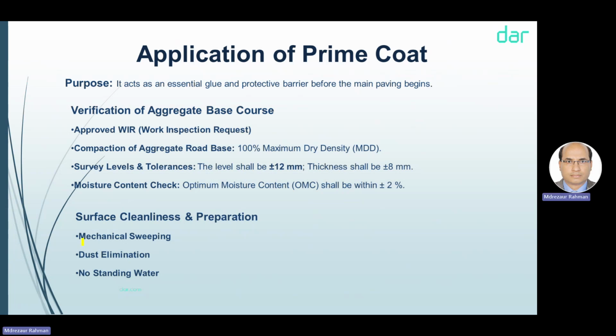So by mechanical sweeper, we have to clean the road completely. There should not be any dust on the aggregate road base, and there should not be any standing water. We cannot start if there is any standing water or any rain.